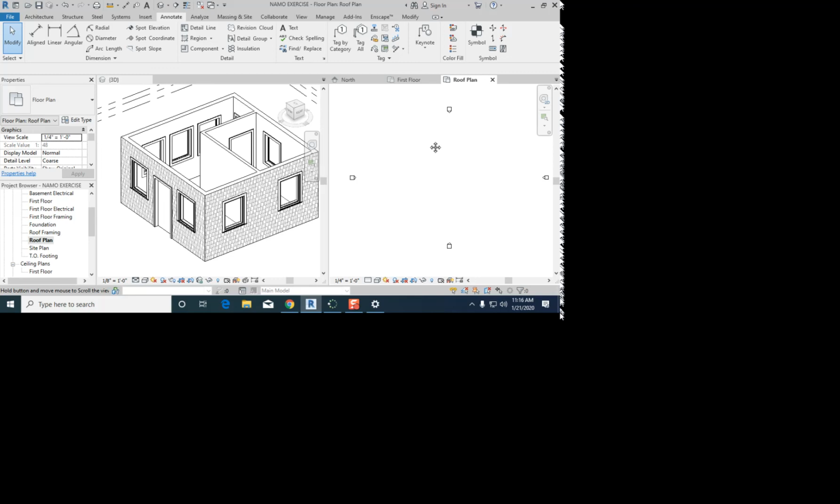And it might look like a blank floor plan. And I'm going to close windows because I have a lot of stuff open. Okay. Everybody at roof? Yes? So one thing that we need to do, because I deleted our second floor, it looks blank, but we can easily get a reference in here. So this is bonus content that we typically don't go over for a minute. But over here in our properties, I want you guys to keep scrolling down until you see something called Underlay. So my screen is going to look slightly different than yours just because I'm zoomed in so much. And the first thing should say range base level, and right now it says none.